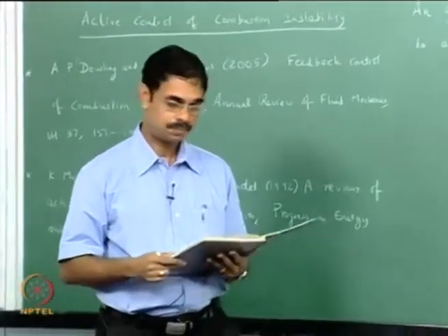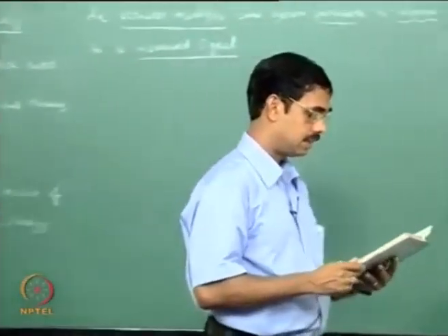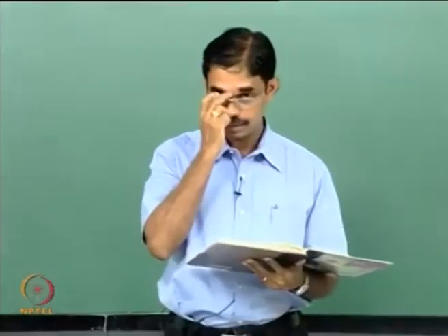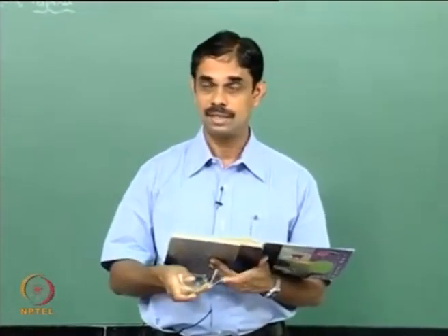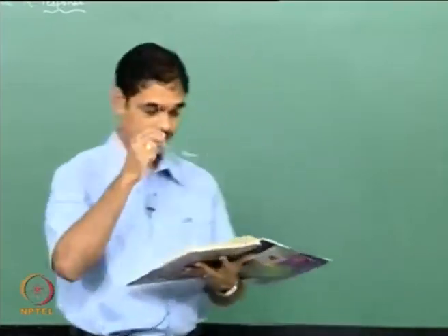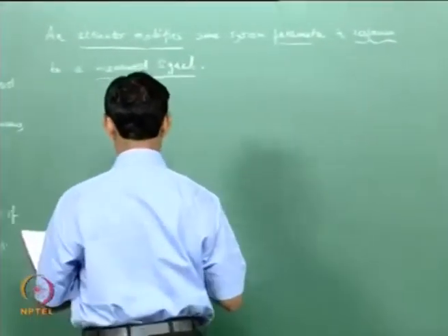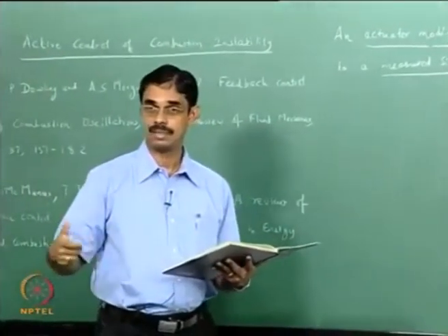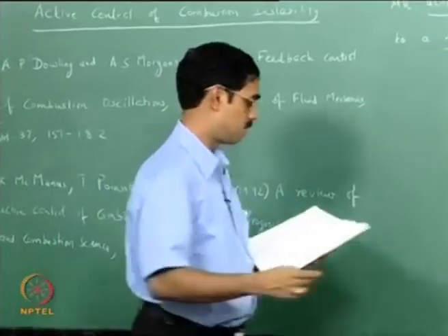The aim is to design the controller such that the unsteady heat release and acoustic waves interact differently. There is some way of interaction and then you want it to interact some other way, okay. So the controller means the relationship between the measured signal and the signal used to drive the actuator. That is actually the meaning of controller.